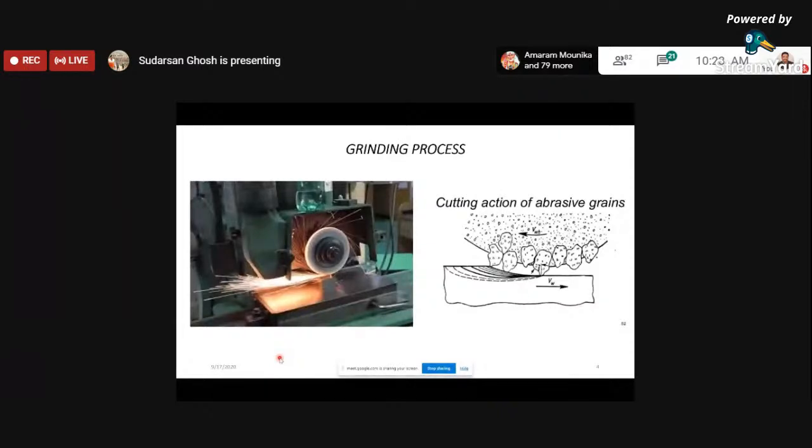So whatever issues we have discussed for machining, the problems associated with the machining process, for the grinding process the same problems exist, or on the other hand, some of these problems become multiplied. So in the grinding process also, the only alternative is to basically use the metalworking fluids during the grinding process.